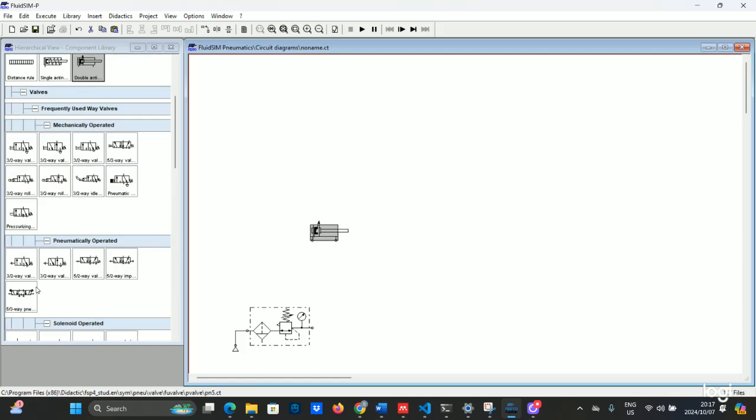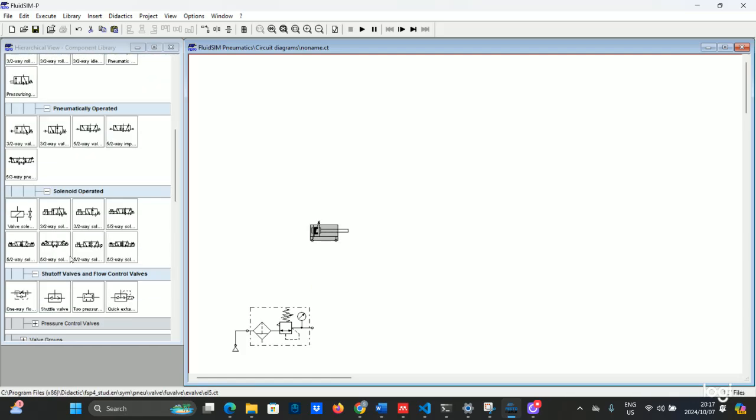Now we need to decide on the type of solenoid valve to use, the 5/2 in particular. As I've probably mentioned before, to control a double acting cylinder you cannot use a 3-way. It's always a 5-way. So now we're deciding on these different kinds of 5-way valves.